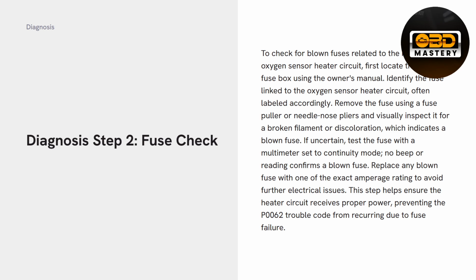It might not even be intact, but just look for that. If it's black and there's no contact, then that is a fuse that you need to replace. So best replace it. That's usually the best way to look at it because fuses are very easy to replace.